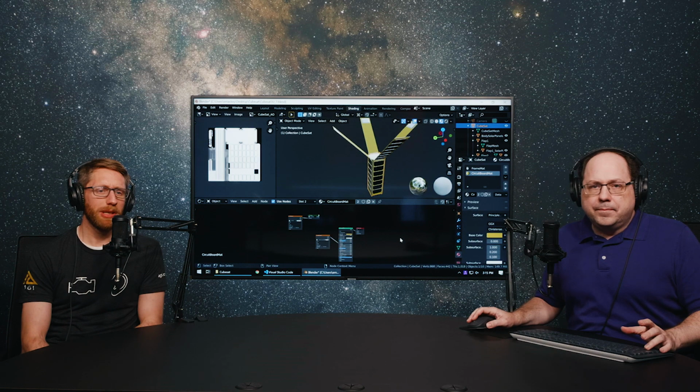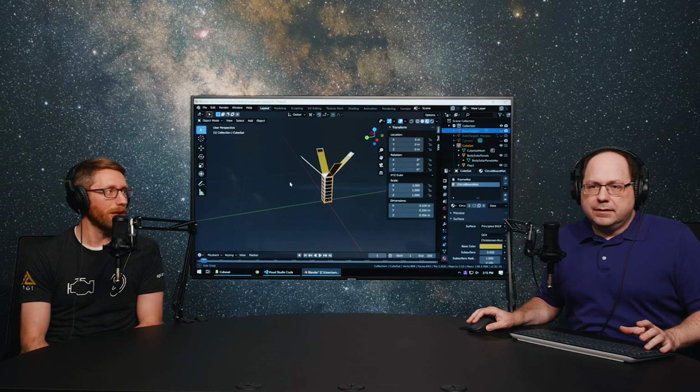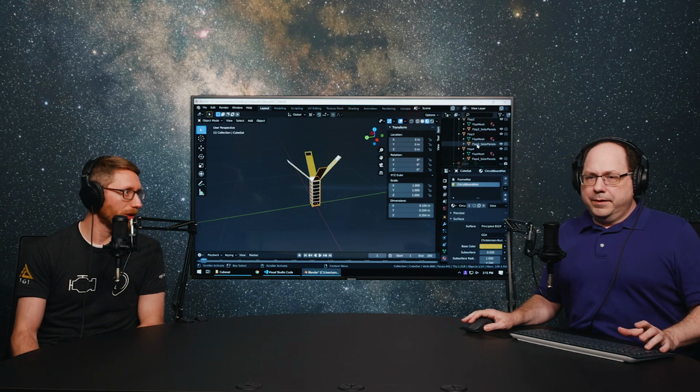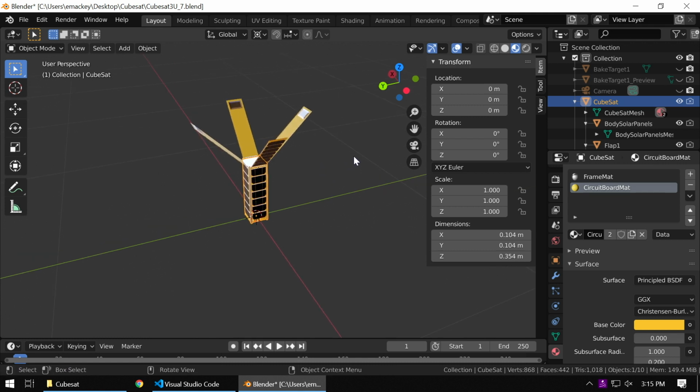Okay. So when we export this, will the exporter pack all, like our occlusion and metallic and roughness, all into a single texture? It will. Okay. So we get that ORM texture for free once we export. Yes. Now that we've set everything up. Okay. And indeed, since we don't have a metallic map plugged in, it's going to bake all white for that channel.